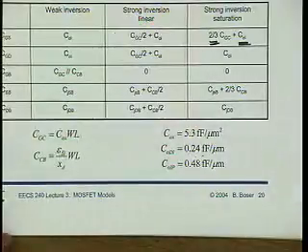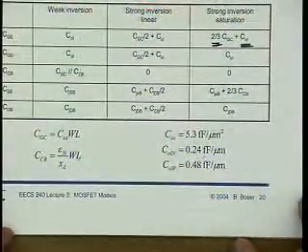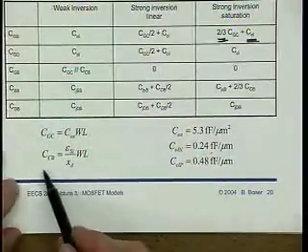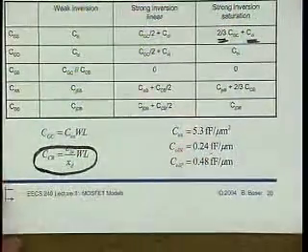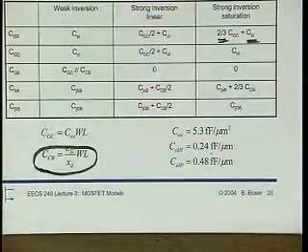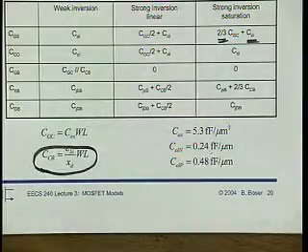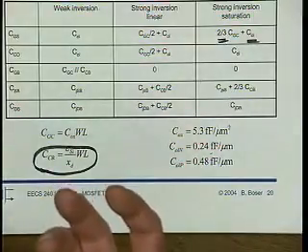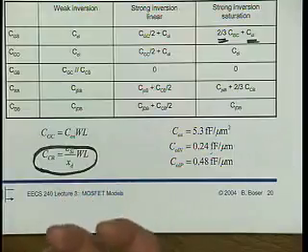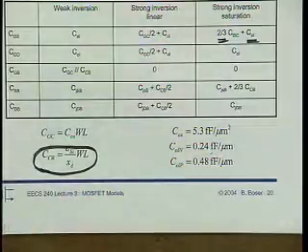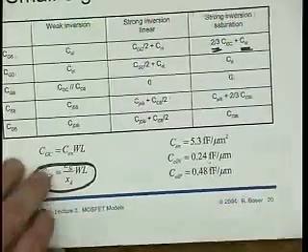The other thing that is often not included in many undergraduate texts is the capacitance between the channel and the bulk. The thing is that, of course, the transistor has the 3 terminals, source, drain, and gate. We are interested in those, but really, charge is stored in the channel, and so there really ought to be a capacitance for that channel, and that is even a distributed capacitance. And so this channel to bulk capacitance really takes care of that.